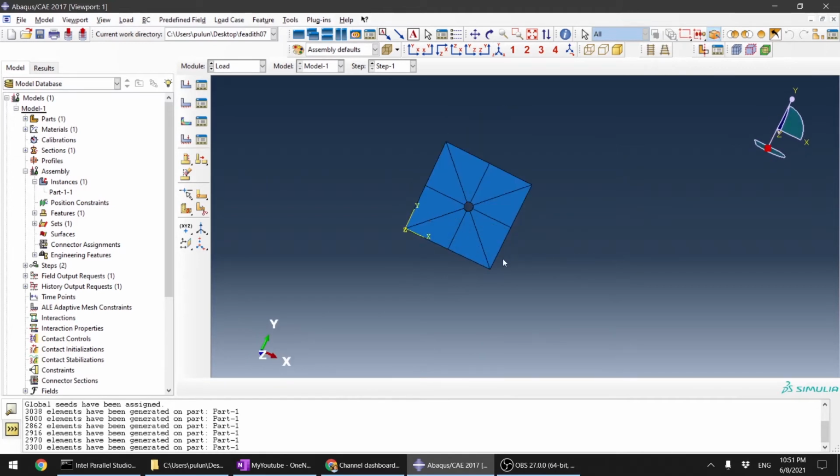In this direction, we are going to fix, while in this direction, we are going to pull in the Y direction. So click here. You can do it many ways. You can do displacement control here. So you fix, while here you can give the force directly, like in newtons, or you can put the displacement, for example, you pull this area 1 millimeter away.